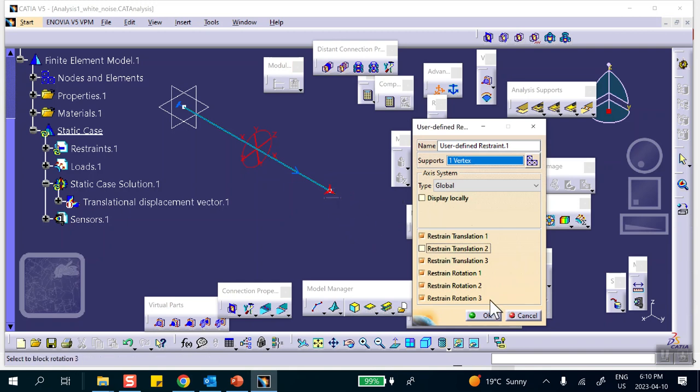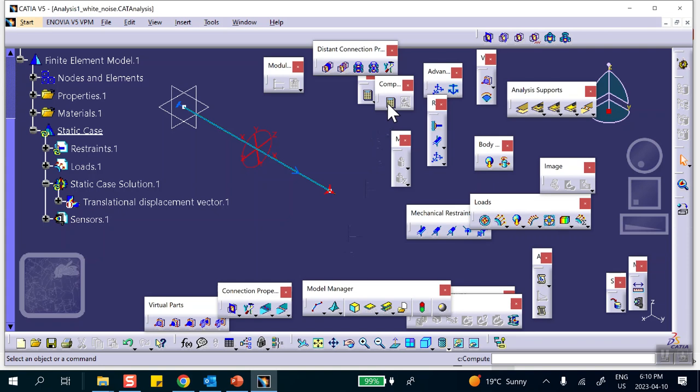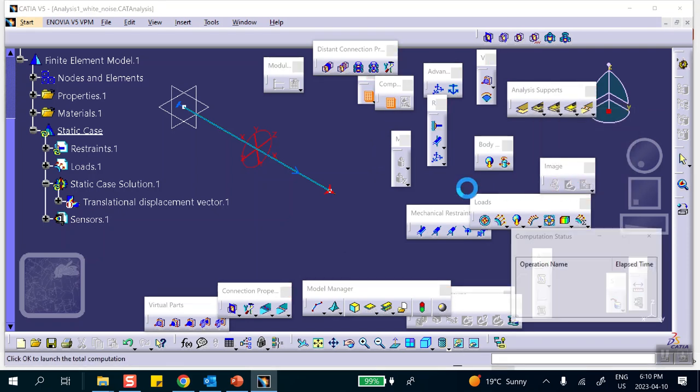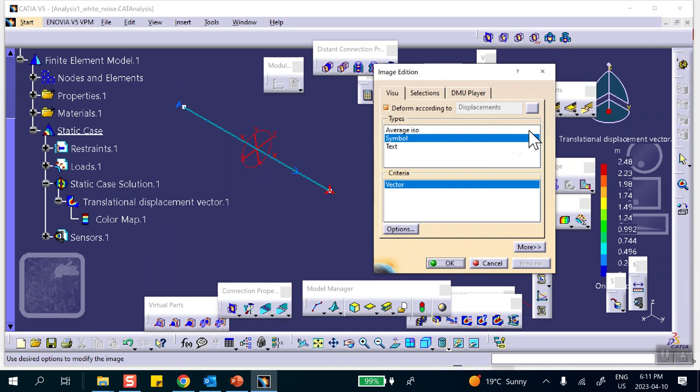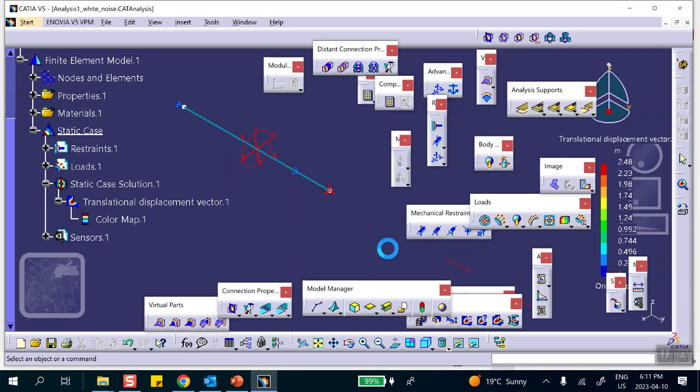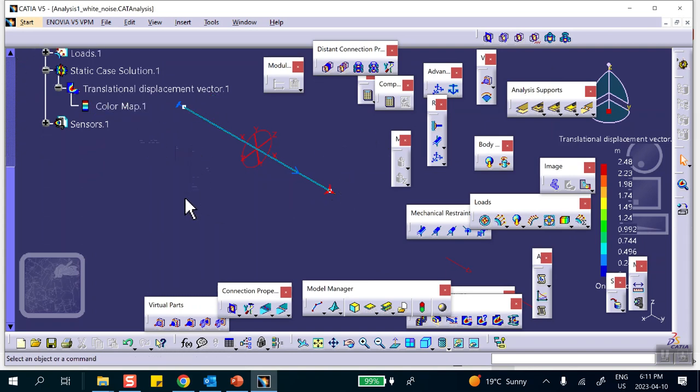It's not going to make much of a difference when you run it. You're going to get exactly the same number as before, but it will take away some of those frequencies that may be popping out when we do the dynamic case. So if you look at this, double click, and you can see that nothing changed, and you get 2.48. It's just that this is not going to go out of plane in any direction, and that's why the frequencies are going to be limited, and that's what you really want. Single degree of freedom system, only one frequency that we are interested in.